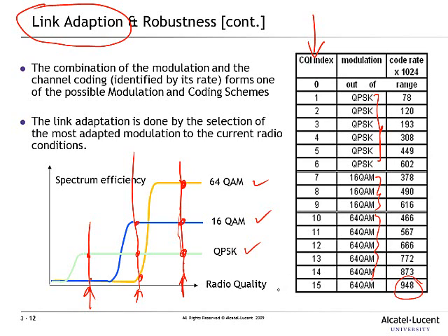And so this corresponds to the best channel quality, the best modulation, and the least amount of error coding. Okay, because the least amount of error coding means the least amount of overheads that you are putting into the data. Whereas CQI 1 corresponds to the worst possible channel quality, in which transmission is still possible.